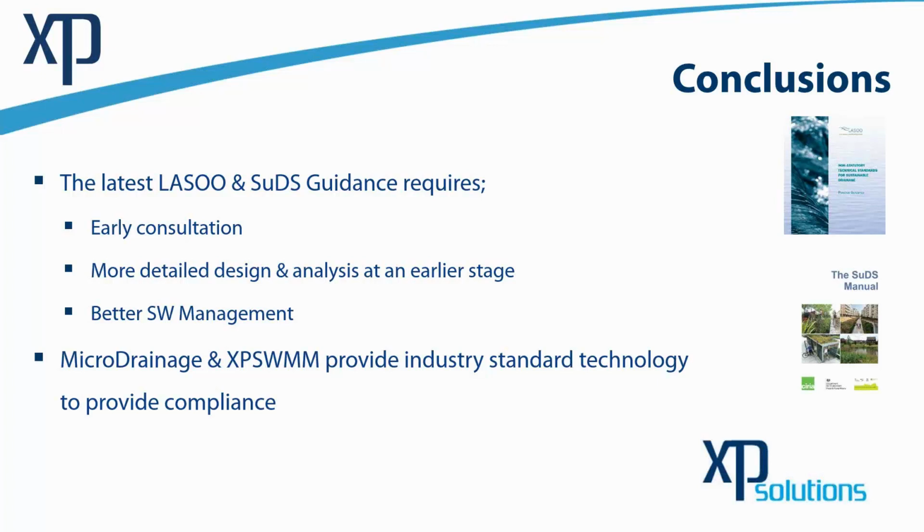So when you're modeling existing scenarios, you could put in full extents of the drainage network if that information is available, as Ludi mentioned. But in the absence of any information, you could always do the rain on grid, which is the worst case scenario approach. And certainly in terms of engaging with people early on and doing something very quickly and easily, that is probably going to be the worst case, and I think it is a good way to think about it.